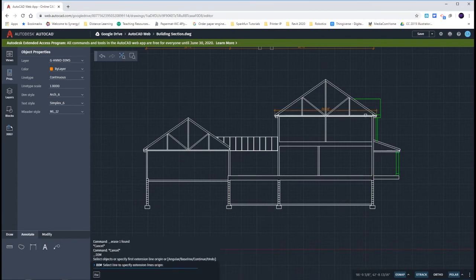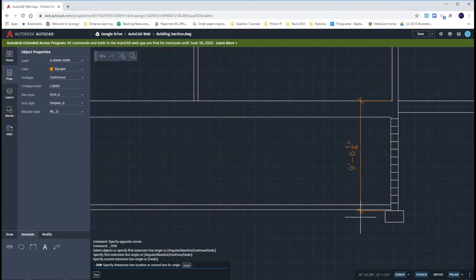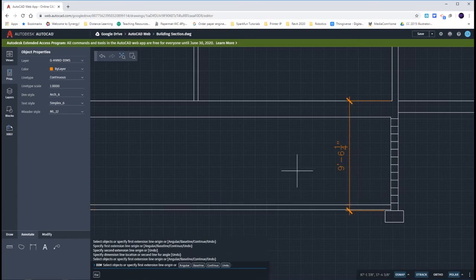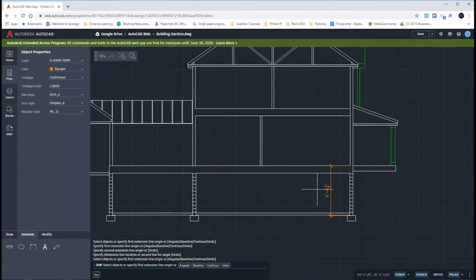There are 3 going to be over here on this side. Now remember, they go from the top of our floor to the top of the foundation footing on this edge. All right. Now what we want to do after we create that dimension is continue, so they stay in line, by using this continue button. We're going to continue this one here coming up.